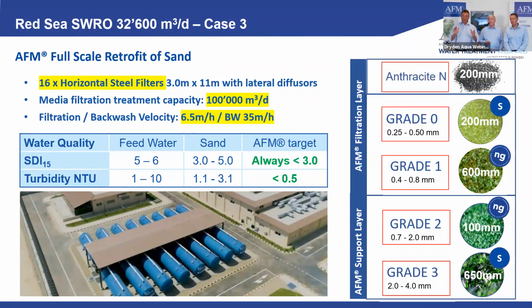But again, you don't have to mess around. Give us just your data and we will do the best layering. Maybe different here is we also add anthracite to it because in this case, the suspended solids load can exceed 30 ppm. This we do quite often, also if you have algae blooms, etc. We will not supply it, but we will recommend it. And we try to get the best solution out of you. So give us the data and we give you our proposal, our solution.